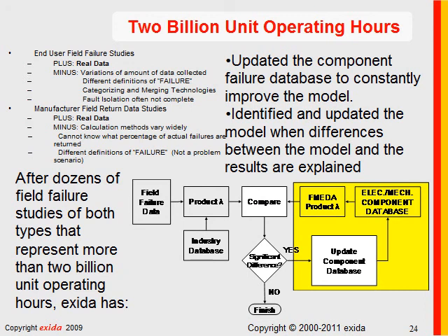Interesting problem. So we were able to learn that the failure modes and failure mode distributions of a conventional power diode are very different when that diode is used in an overvoltage protection application versus a power supply rectifier. And we've entered that into the new database, and we're accounting for these failures now as we move forward. There are many, many examples of this type over the years, and these are things that even the current international standards do not include.